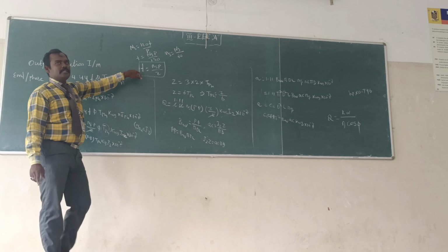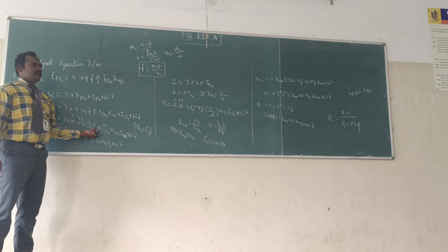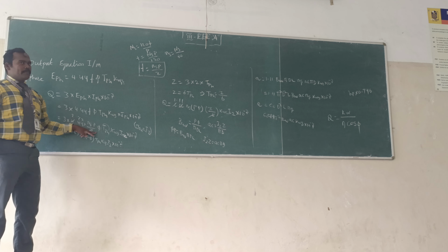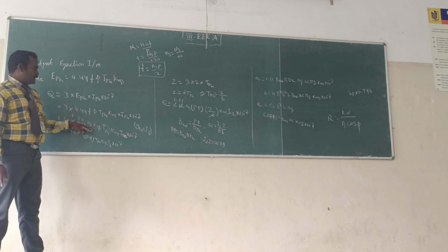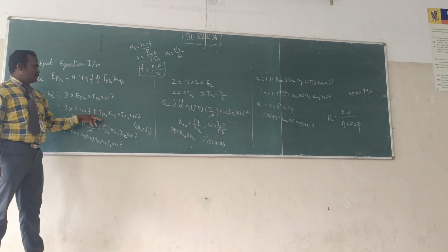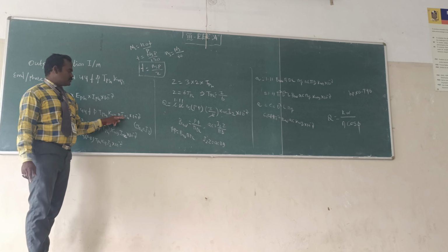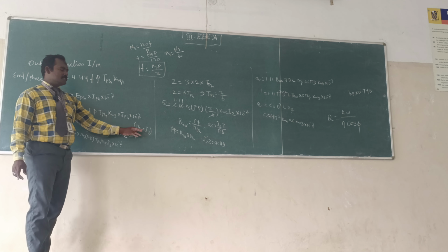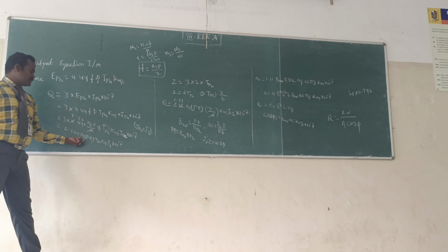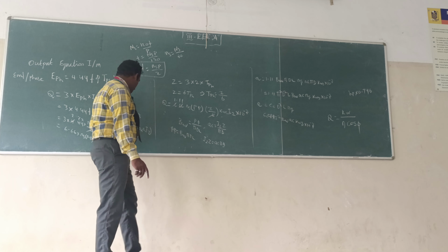Why are we finding f in terms of P? Because we need to substitute the total electrical loading and total magnetic loading. So Ns P divided by 2 replaces f. Similarly, the current per phase is the actual flow of current in the phase, so I phase we can replace in terms of I Z, and you can substitute it, but you will find there is no Z term.